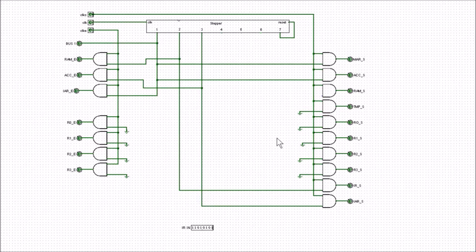So this is possibly a eureka moment for some people. What we're looking at here is the interface between the software, which are the instructions here, and the hardware, which is the logic here, which we've still to build. So the new register is called the instruction register. An instruction register contains the program. So the program tells us how we should connect all the sets and enables. So in effect, the program tells us how we should move information round about the CPU.